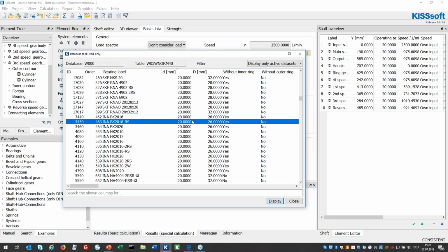If you use the 2019 release and compare the bearing inner geometry approximation between the previous and the current release, you may find a much improved approximation with the current release. Also, of course, we always recommend doing some tests before you switch between the previous and the next release, just to be aware of any possible changes.